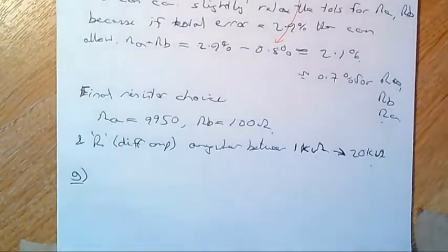And it talks about if you design the circuit in part F and it's been optimized to drive the production test equipment, in other words, the 1 volt RMS, consider the worst case peak signals appearing at the output of the cartridge, combined with an audio band covering 20 hertz to 20 kilohertz, and describe any limitations this circuit might have when playing vinyl records.